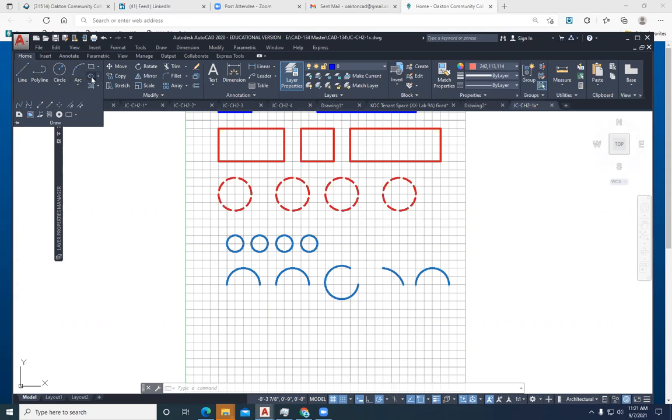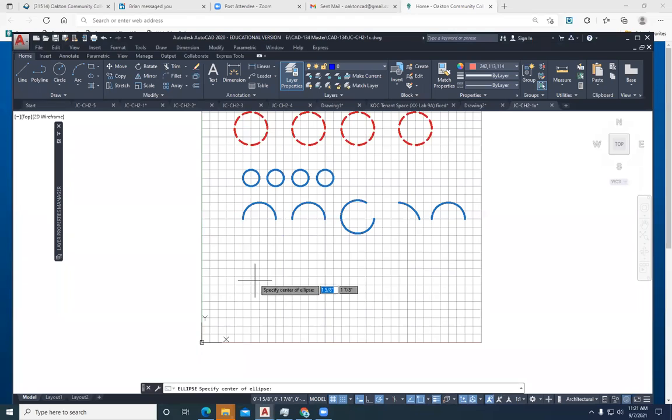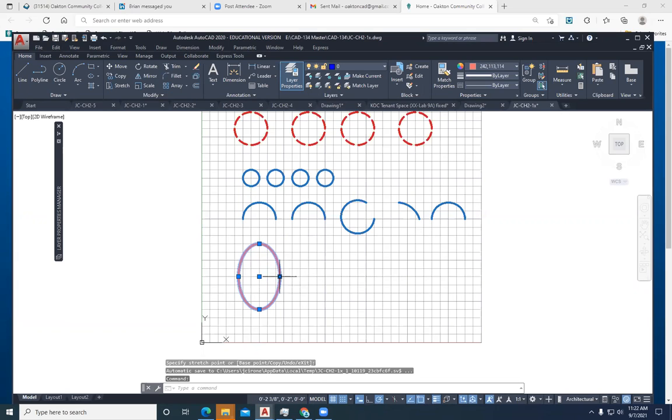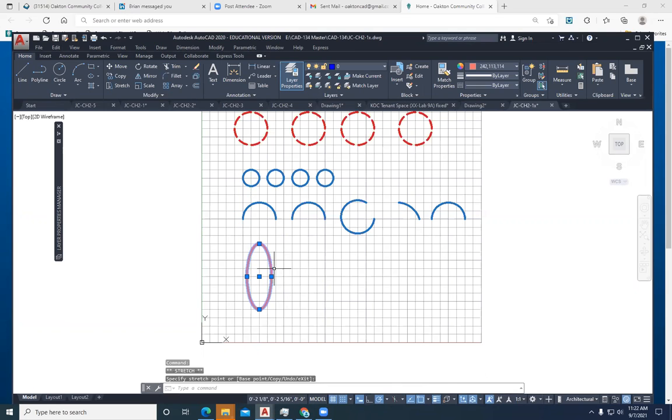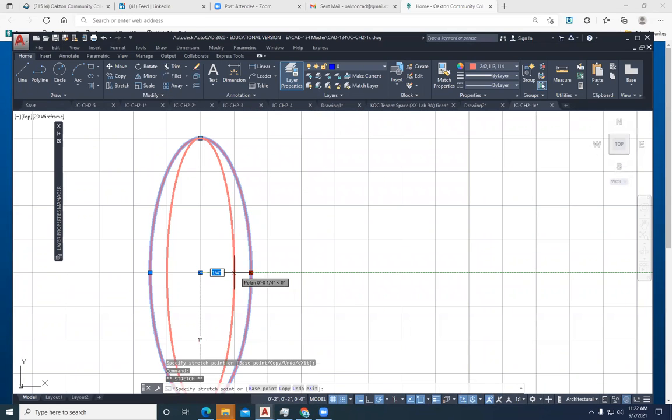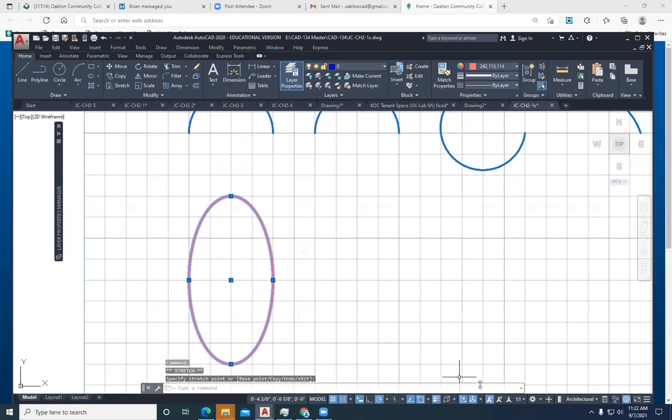I see it now. So I'll go with the center ellipse command and I'll pan and then I'll say, okay, this looks about good. And I'll go up in the y-axis first, and then I'll just tweak it in the x-axis. And there we go. I can move it. I can adjust the size if I need to with grips. If you are getting these green snapping points, O snaps, and they're not going where you want them, sometimes you have to turn off O snap.